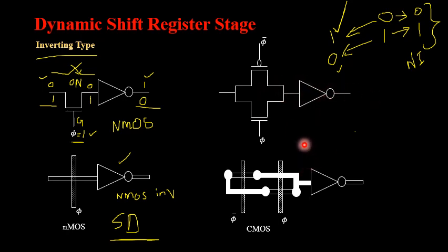So once again it is a circuit plus the stick diagram, because this I have not represented in terms of a stick diagram. If you want to represent all these things in terms of a stick diagram itself, this is anyway a stick diagram. CMOS inverter, replace it with a CMOS inverter stick diagram, wherein I will have a polysilicon vertical layer, then two layers of diffusion type, that is P type of diffusion as well as N type of diffusion, and the polysilicon layer you have to cascade with this particular metal layer, so that it is shown in terms of your stick diagram of a CMOS inverter.